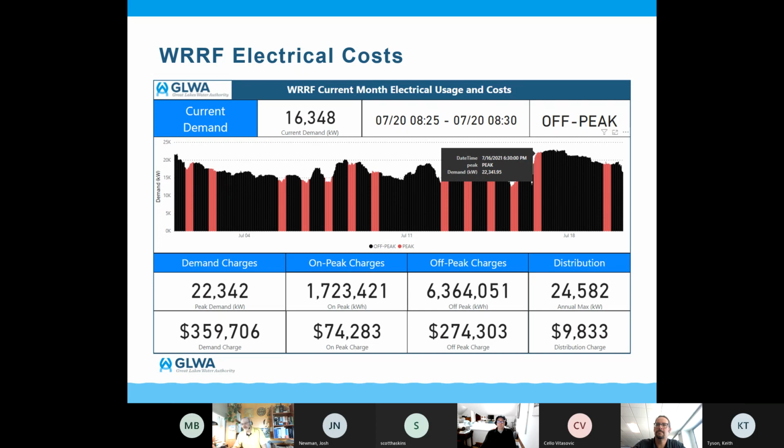Here's another one. Let's say we have a situation where our peak and our off peak are really, really different. So peak shaving, bringing down the big demands like this to get these troughs, let's say they were peaks because they're during the afternoon or so, and there's maybe a big demand for water or whatever. If we can shave that peak and shift it, we might have exactly the same amount of energy demand, but it would cost us a lot less. Well, guess what? The folks that are interested in the emissions side of energy, specifically greenhouse gas emissions, may not find that to be useful or cool at all. But from a cost point, it's a huge driver.